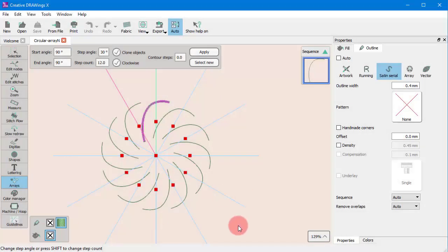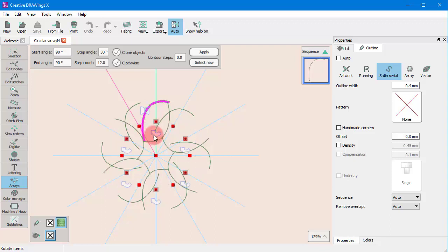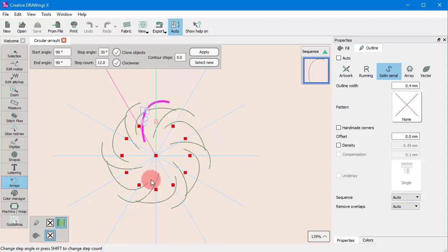When placing the mouse on top of any control mode, action handles appear. These handles appear highlighted not only on the current clone but also on every 2 clones. It is like an X2 pattern where for every 2 clones, one of them is affected. Now, press the rotate sign to rotate by 90 degrees or choose the mirror sign.